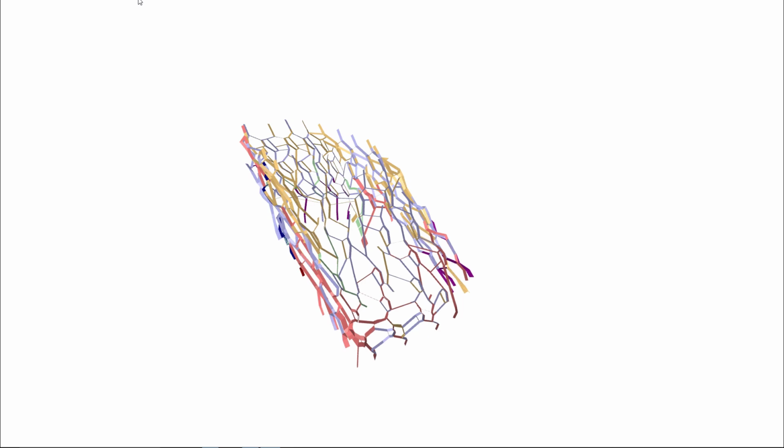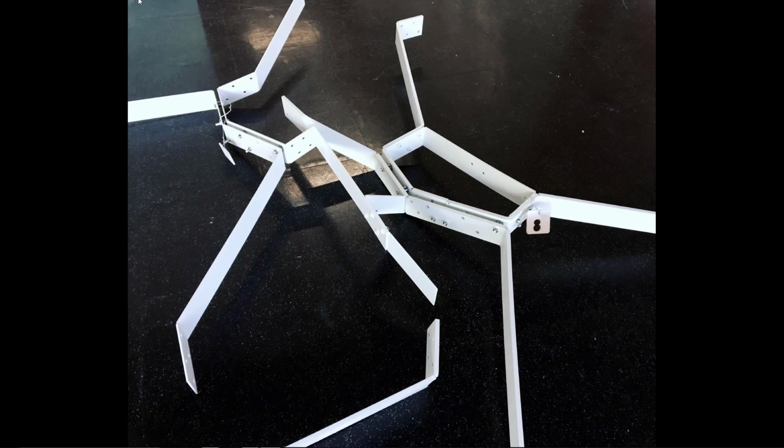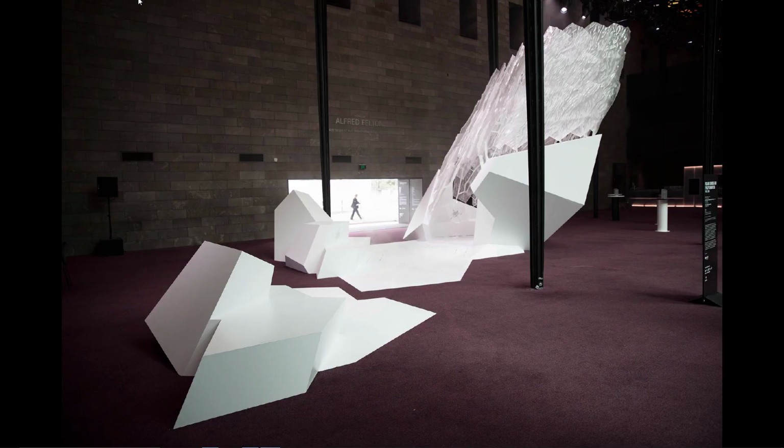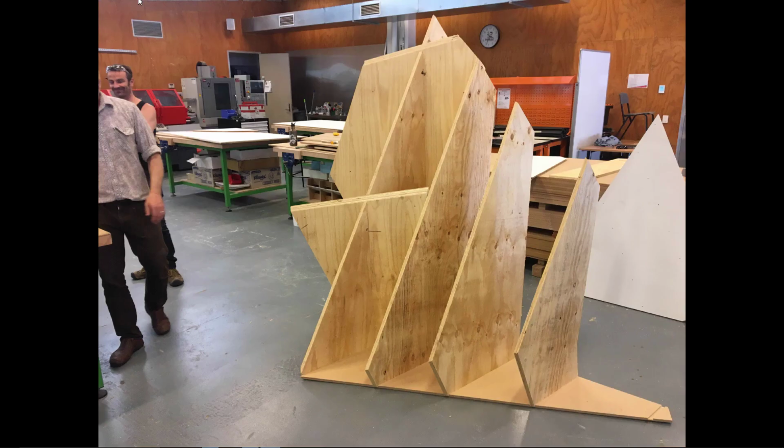And then we translated that steel into the thicknesses and dimensions. We had an unroll script, which I guess isn't all that exceptional these days, and sent it off to the fabricators. Every single one of these steel members, there were 367 of them, was individual, all different forms. So in order to put them together, hopefully I got some photos of this.